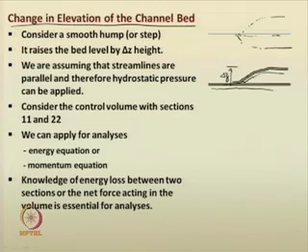We are suggesting a smooth hump here. The rise in the bed level is smooth, streamlines are not bifurcated or disjointed, and they remain parallel in that particular flow. Thereby, we can use hydrostatic pressure conditions to evaluate the pressure in the liquid.